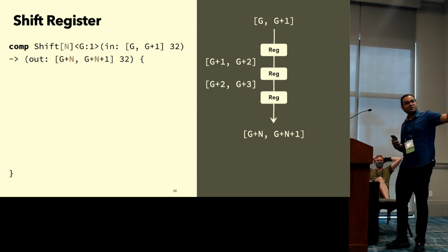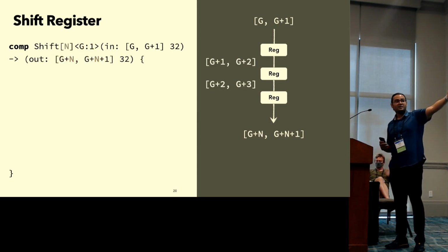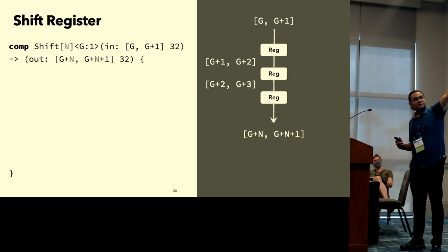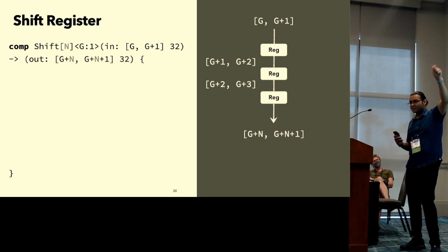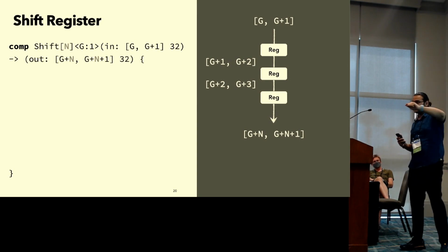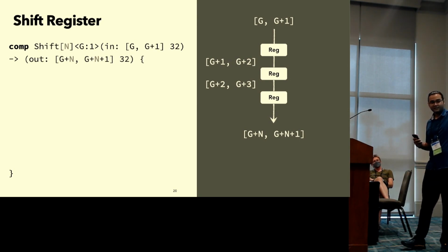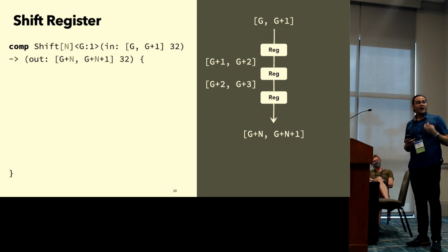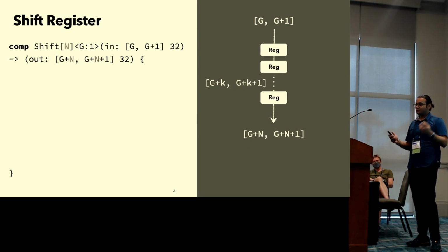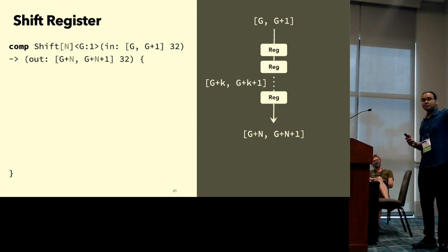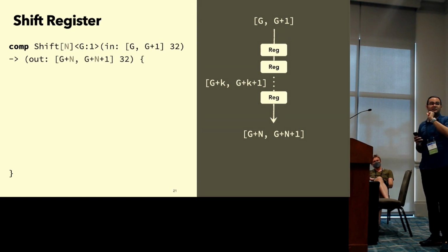Next, the other thing to notice is that when we build one of these shift registers, that signal is in the first cycle. Once it goes through a register, it's delayed by 1 cycle, so it's the second cycle, the third, and the fourth, and so on, right? And so if we generalize it to a parametric design, for each wire, the signal is available at the kth cycle. So if you've gone through k registers, that signal is available in the kth cycle.